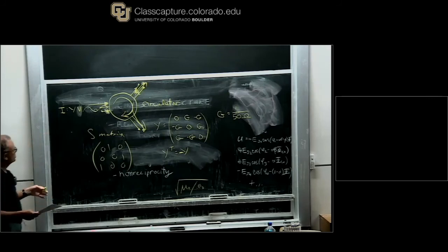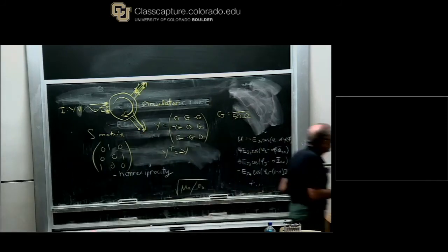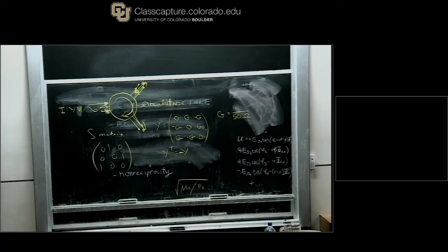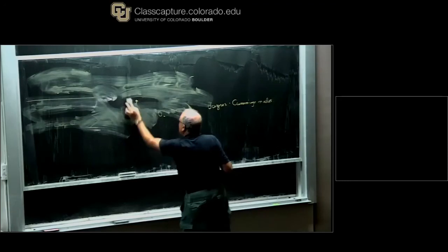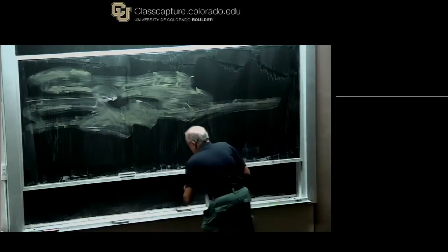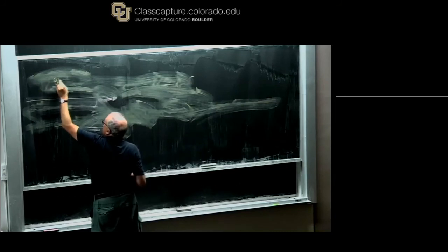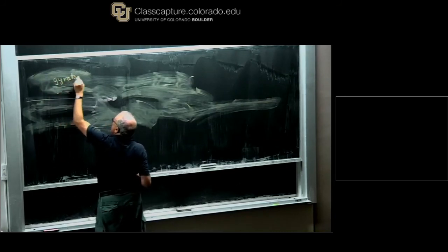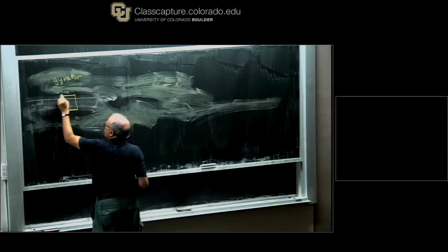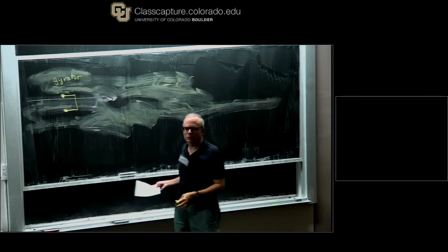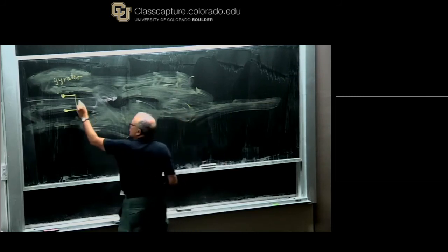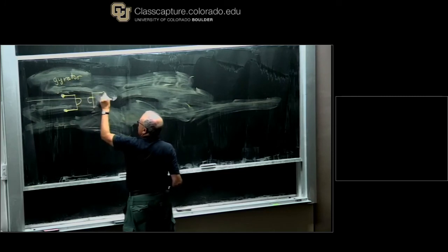Now, let me say the way this is dealt with in theory, in the theoretical work, is to choose actually a simpler canonical device. And historically, the one I'm about to state was introduced first, and that's the one we'll quantize, or I should say make a Lagrangian for. And that will be the gyrator. Gyrator is, by definition, a conceptual device in the same way that ideal capacitor, ideal inductor, ideal transformer are. Here's a new object, has this symbol for it.